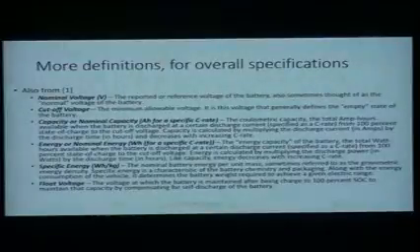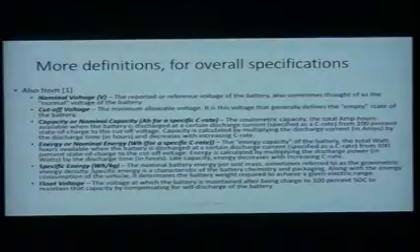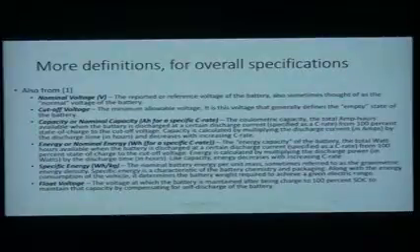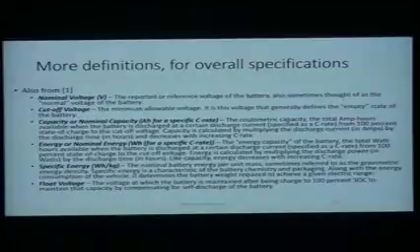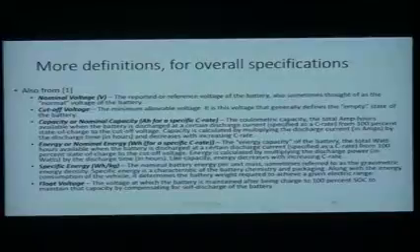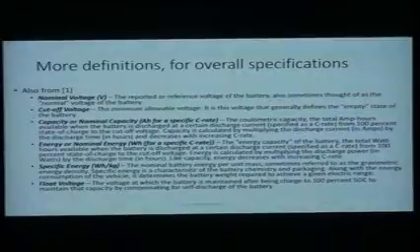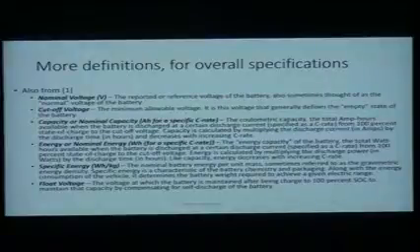The energy rating is done not in joules, which is the unit of energy. It's done in watt hours, which is power times time. Now, just like for the capacity in units of amp hours, the watt hours tell you how much power you can get out by taking the amp hours and multiplying by the nominal voltage of the device, because voltage times current is power, right? Amps times volts has unit of watts, okay?